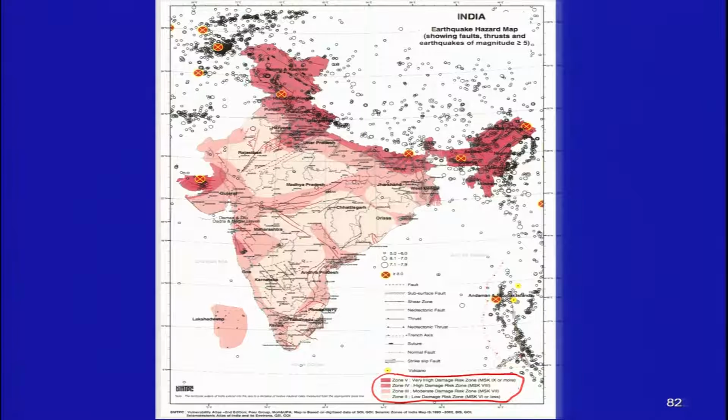But one thing I feel is that we still do not have very good data from this region, the Narmada zone area, which partly falls in Gujarat and then goes into Madhya Pradesh. We do not have good data in terms of historical earthquakes, but this zone will also be considered, and it will fall in either 4 or 5 if we get more data. So we can keep improving the zonation map if we have more data available, or we incorporate or generate that data by doing more research in this region.